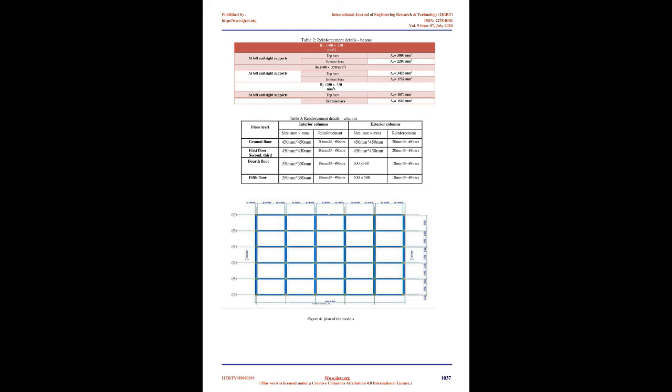Assessment of the pushover method procedure. The pushover procedure is performed to analyze the relationship between the lateral base shear and the roof displacement of the building. The pushover curve for the structure begins with the initial linear range, in which the frame members deform in their elastic behavior, and continues into the inelastic region, where the beam and column members start developing plastic hinges. If the lateral deformation continues, other plastic deformations happen in the structure.